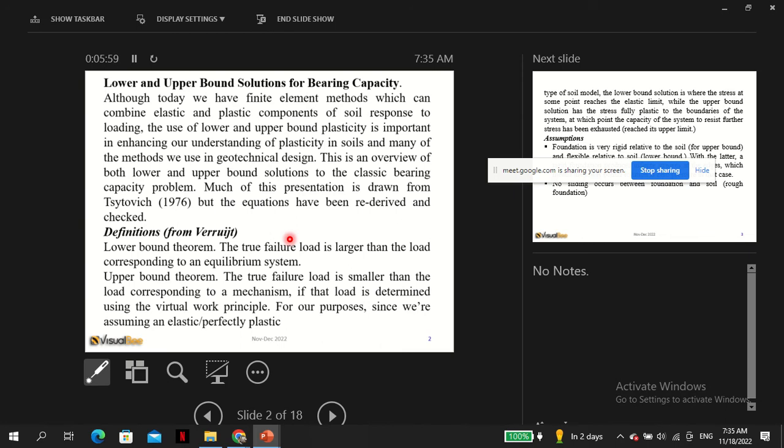Okay, we are going to talk about this in detail. So you can now see why I said that we apply a higher factor of safety to bearing capacity, between 2.5 and 3. In fact, for design of foundations, we always apply a higher factor of safety, usually between 3 to 6, depending on the degree of uncertainty.